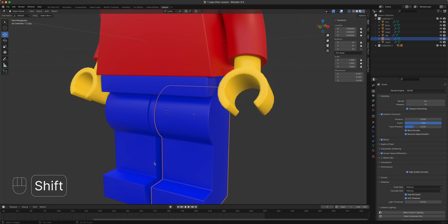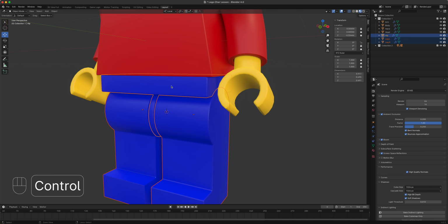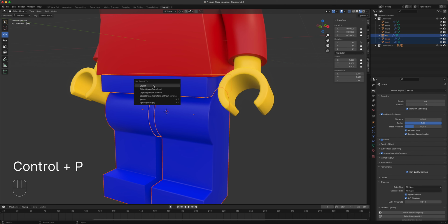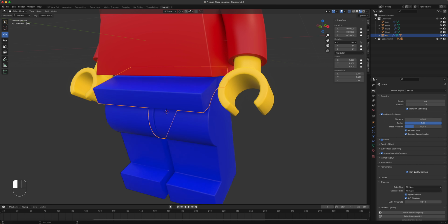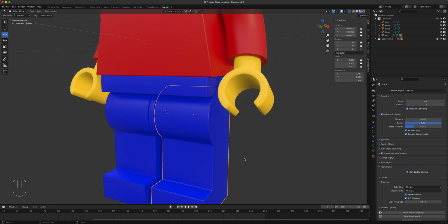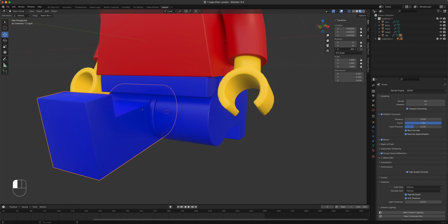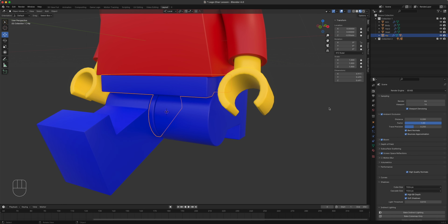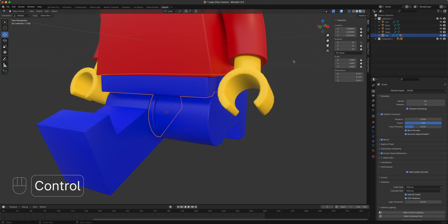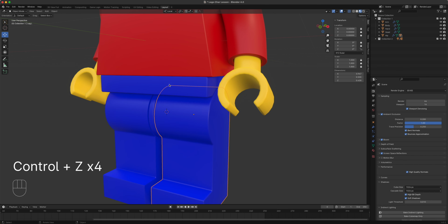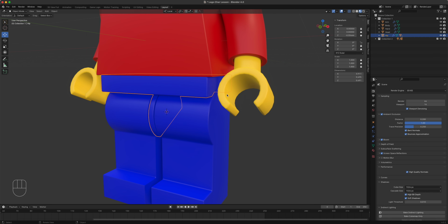Okay, and this one is the hip. So if we select both legs and then shift click the hip last, Control P, set parent to object. So now whatever we do with this, which is X, both legs kind of follow. Just for the sake of demoing, if we go like so, and we want to animate, there we go. So they follow now. Undo, undo. All right, so they're all set here, everything we need.